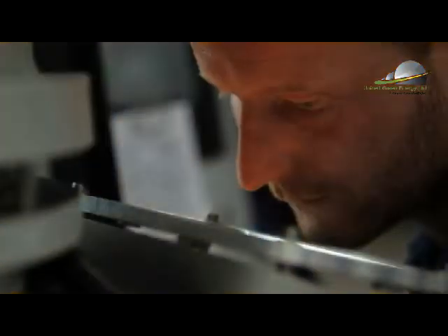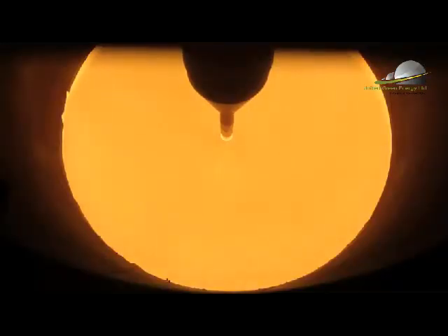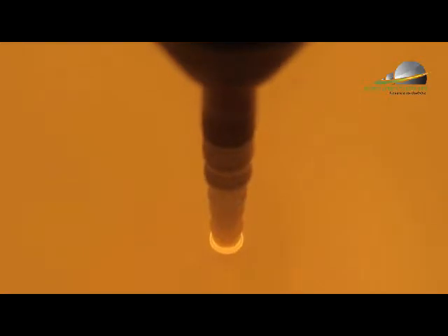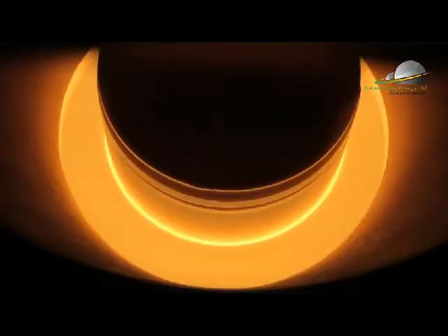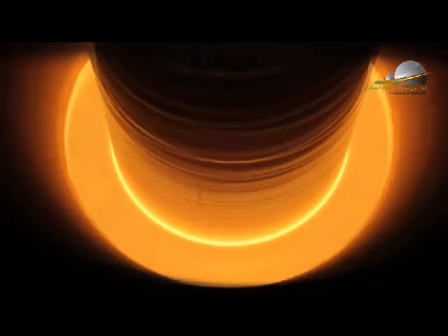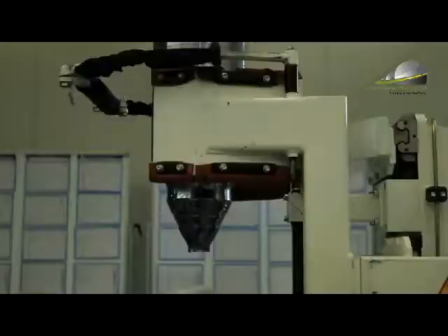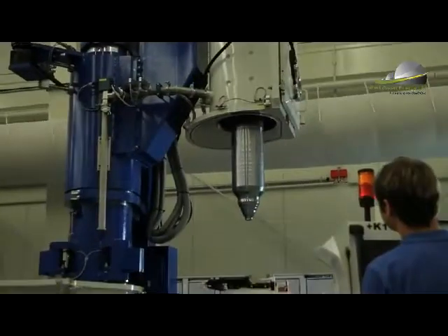In special ovens, raw silicon is melted at temperatures of over 1,400 degrees centigrade. A thin rod, known as the seed crystal, is then submerged into the liquid raw silicon and pulled back up very slowly. At this step in the process, the liquid silicon accumulates on the seed crystal and solidifies. Over 4 days, a silicon rod of up to 2.8 meters length takes shape.